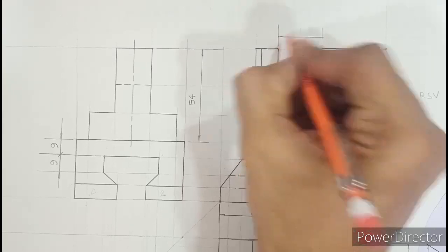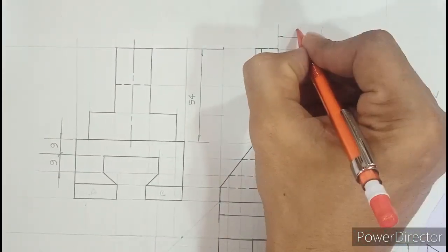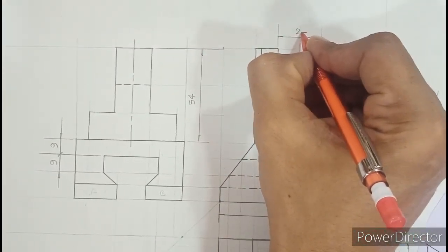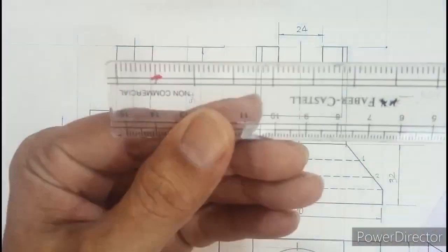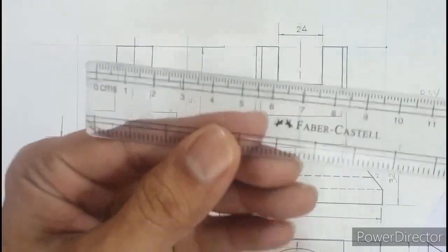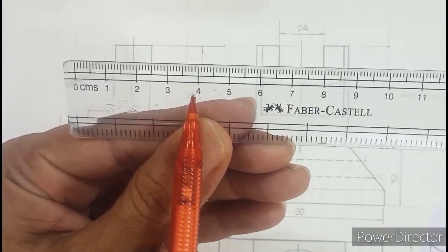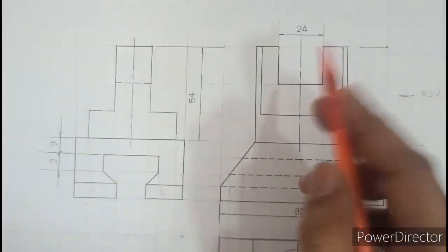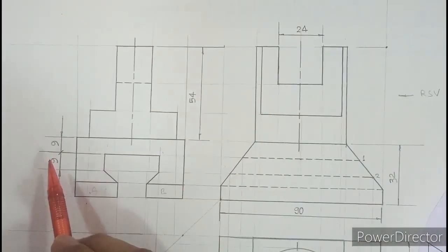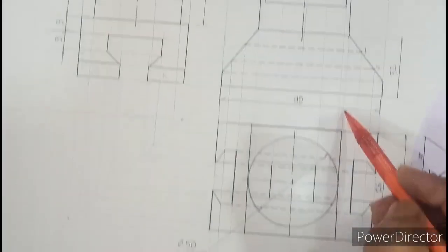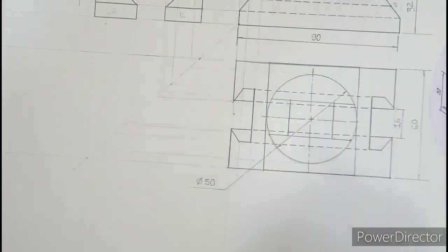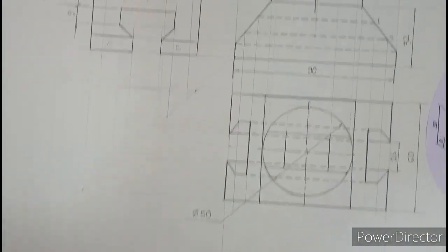We'll show the arrow mark like this. When you write 24, you should be aware of 4. So 4 should be written compulsorily like this as per ISO standard. If you look at the scale, 4 is shown like this. So as per ISO standard, we are showing the 4. Now if I count the dimensions 1, 2, 3, 4, 5, 6, 7, 8, 9. So one more we need to show.